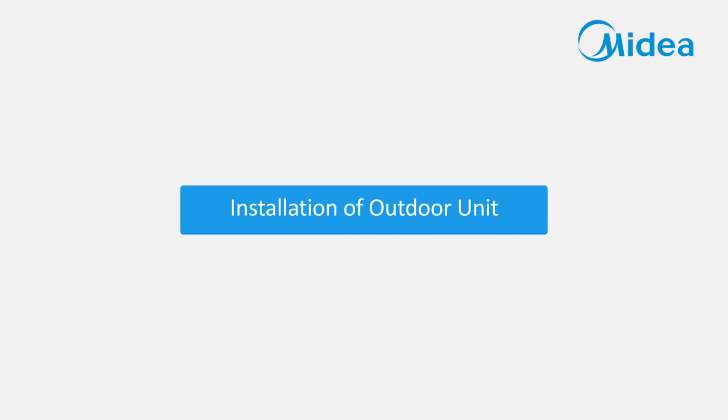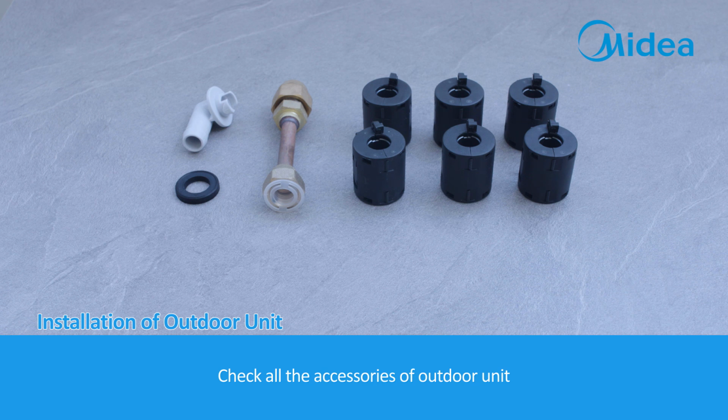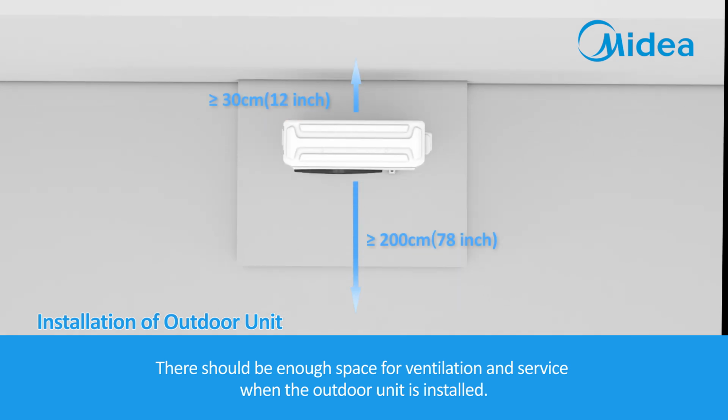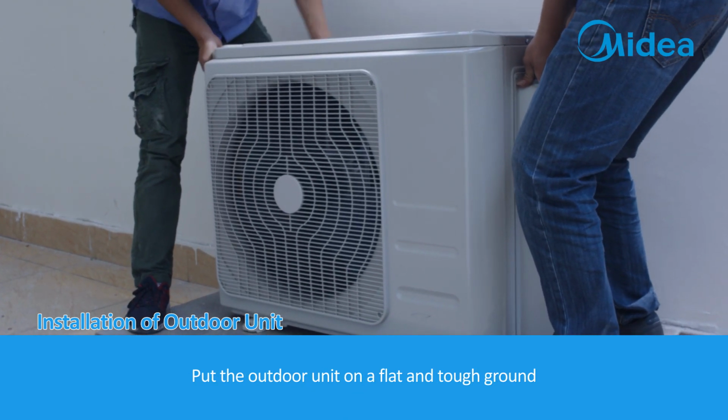Installation of outdoor unit. Check all the accessories of outdoor unit. There should be enough space for ventilation and service when the outdoor unit is installed. Put the outdoor unit on a flat and tough ground.